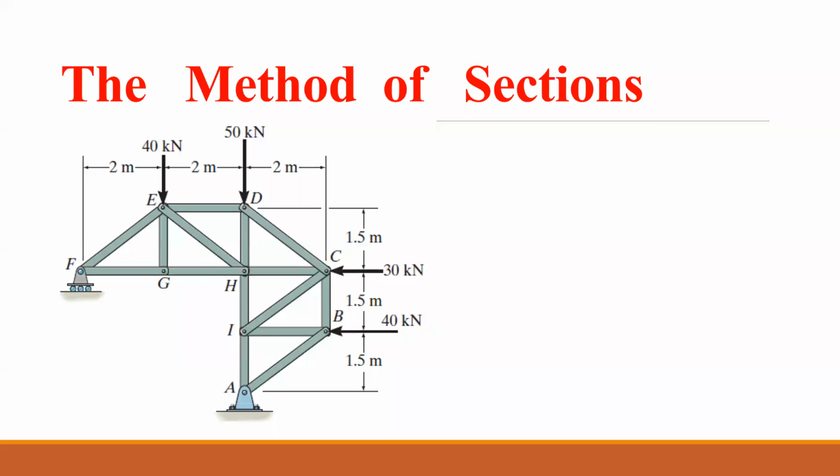Hello everyone, today we're going to apply what we learned in method of joint and method of section to solve two problems and find internal forces in the trusses. So we have different forces. Some of the forces are external forces, like reactions or external loads like this, and some forces are internal forces. It means they are inside the member. So when we talk about analyzing the truss, we usually mean finding the internal forces.